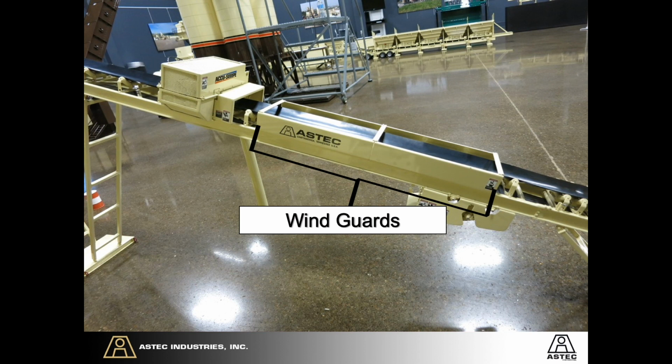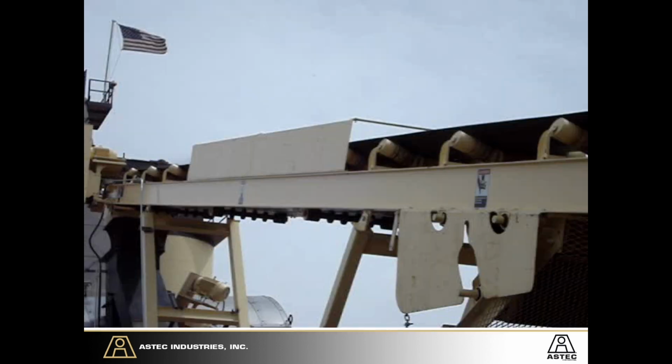Here's a good picture of the wind guards that we talked about. It keeps the weighbridge hidden, so it's easily disguised, and it usually is not maintained very well because of that. You can see, here's the reasons in this picture, and it gives a little bit of an illustration. If you can see the wind on the flag, how it's blowing that flag straight. If we did not have these wind guards here, we'd get belt slap, which would give you inconsistent belt readings when you tried to do the zeros. So it could cause you problems when you're trying to make mix.